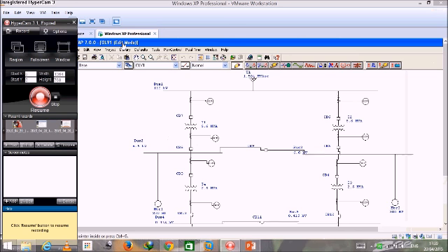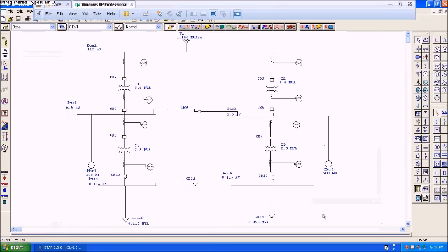So now here I'm going to show the load flow analysis. Here you can see the values of load flow, which are red in color. You can see the impedance values which are given by j, and similarly the current will flow from upside to downside. And now we will show you how we will put the settings of each and every device.